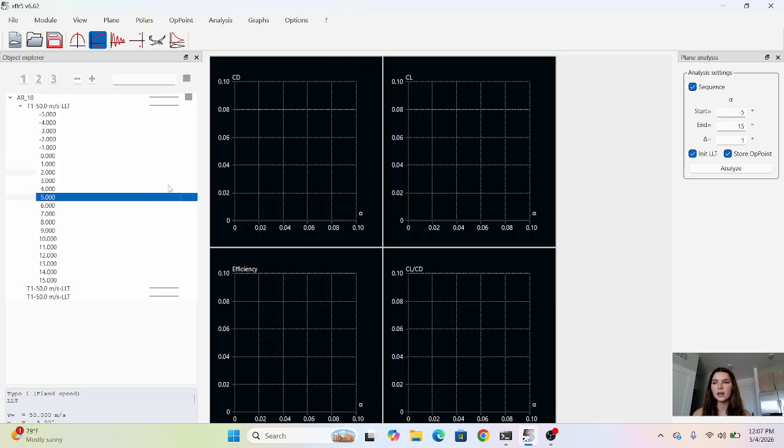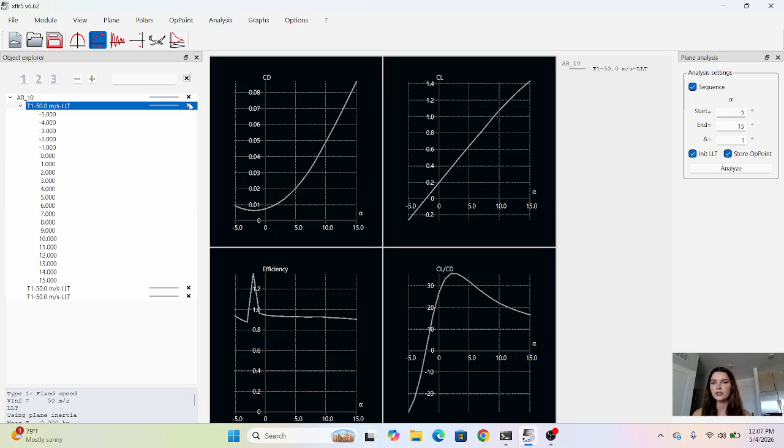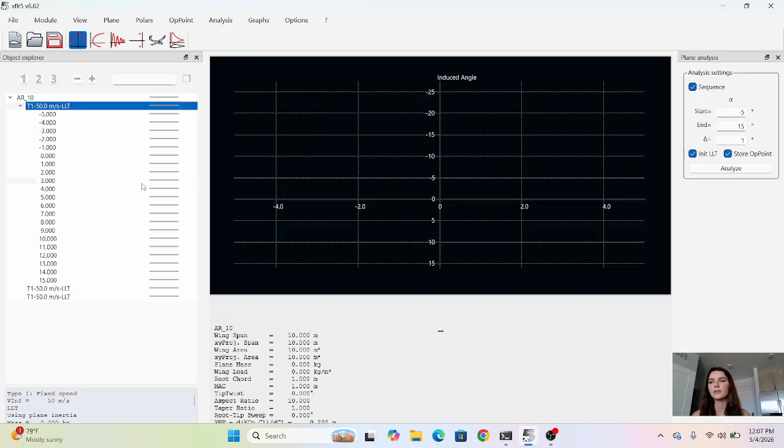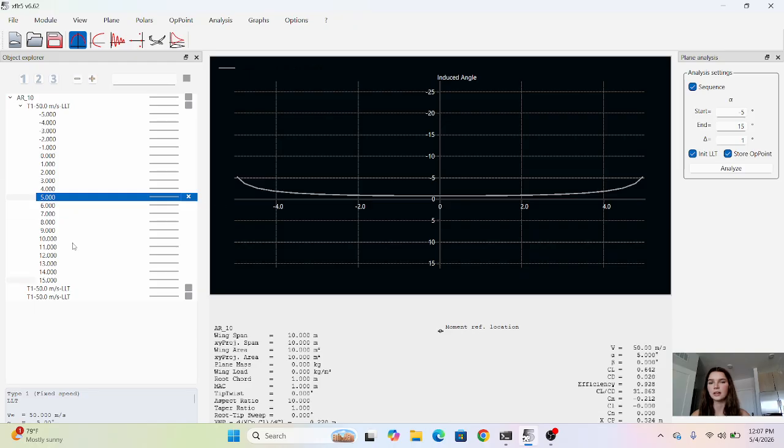So remember back here I showed you guys how to do the second part, which is plotting CL, angle of attack, CL over CD, and so on. Now is the part where we want to know what happens specifically at 5-degree angle of attack. So you just want to unselect it and then reselect it. You can make sure that all your stuff is correct by looking at the aspect ratio it gives you, and all your values. Make sure that everything's making sense.